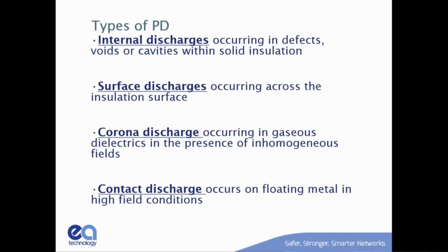But the nice thing with corona discharge is that it's destroying the air molecules. We have lots of replacement air molecules, so they come in, they replace it, they get destroyed, and you have this constant flow of molecules, and it doesn't build up. It doesn't get worse. It doesn't flash over. So we want to not get too excited about corona. The only reason we want to know about corona is so that we don't accidentally tell a customer, you've got surface discharge, which you need to fix, and it's actually corona, and he doesn't need to fix it. He may want to fix it for other reasons, and you might want to tell him it's there, but you want to be able to tell him what kind of discharge he has.